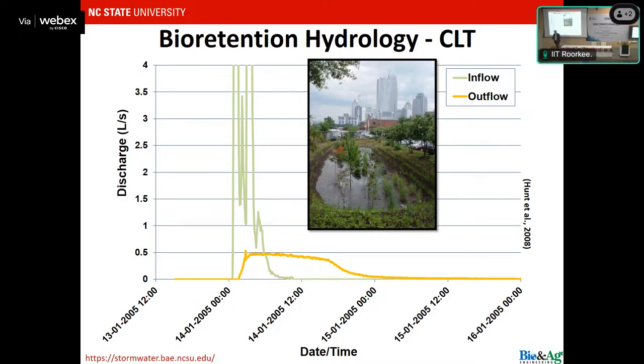Now, obviously, this graph is about a 29 millimeter storm, so it's a medium-sized storm. This graph shows a really high peak flow, and it shows how it was squashed. All right, it was dampened. But what is hard to tell is you don't know how high that peak is. If you integrated under the inflow curve and compared that area to what you integrated under the outflow curve, guess what you'd find?